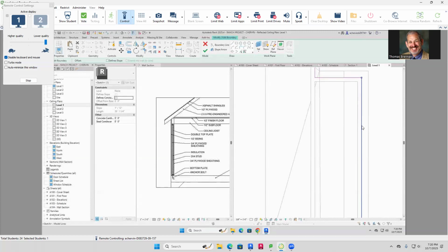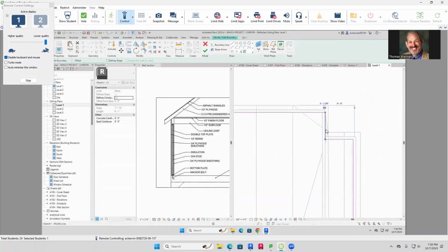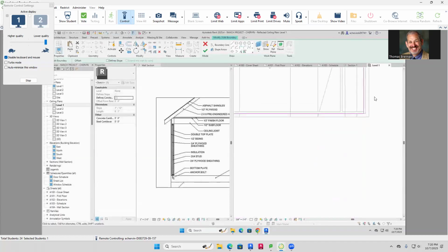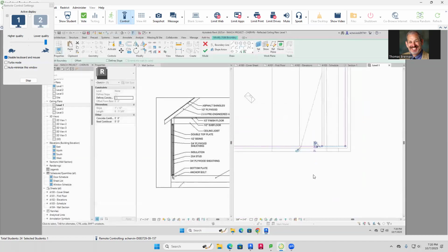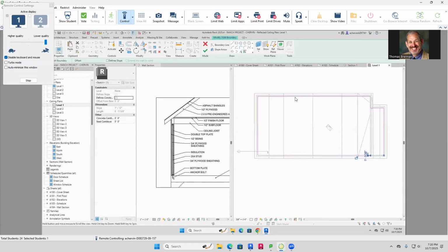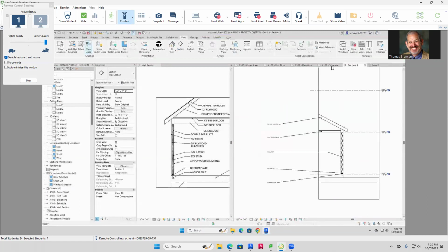When you made the ceiling, you chose the outside wall. That's why it's showing. When you make your ceiling, you always make the ceiling go to the inside wall, so it's not visible out there. That should do it. Green check mark.